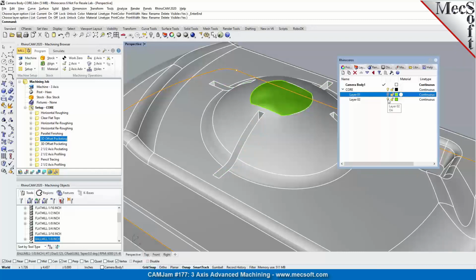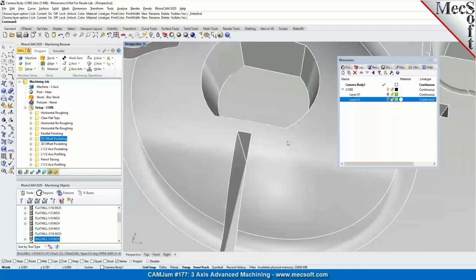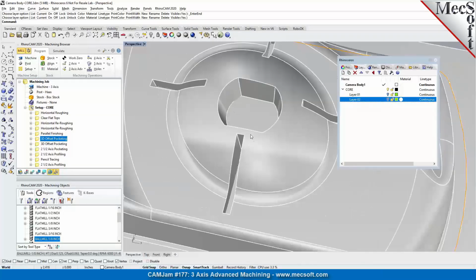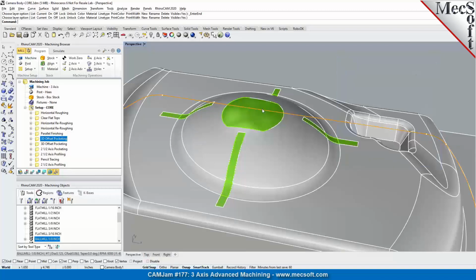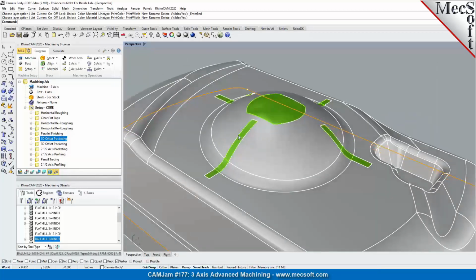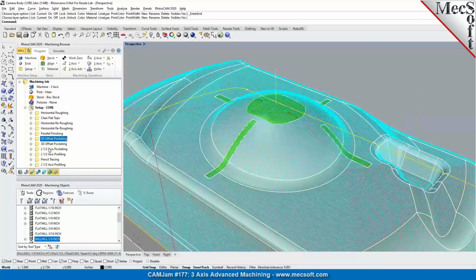In this particular case, we've masked them. You can see there are cavity pockets here on the camera body, which we've created surfaces to mask or cap. So when you generate your roughing and finishing toolpaths, and if you have these surfaces visible, the cutter will not dive into those pockets or cavities. So you can use them for programming your roughing and finishing toolpaths.